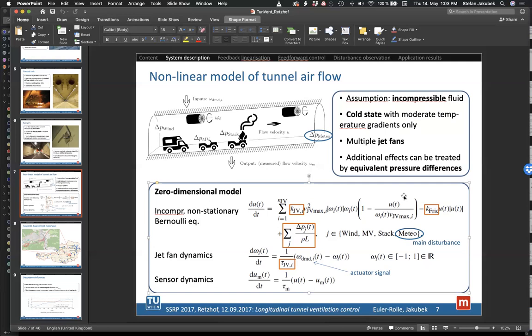You might remember that I told you that the lead derivative LG can be 0 sometimes. And in this case, if the fans are windmilling, so if the rotational speed of the fan is just good enough to make this expression here 0, so you can see there's the flow velocity, there's the angular velocity of the fans, there is some constant here. If all this is 0 at this point, so if the fans are windmilling, you cannot control the flow. This is also one problem. And then, of course, linearization does not make sense because in this state, the system is not controllable.